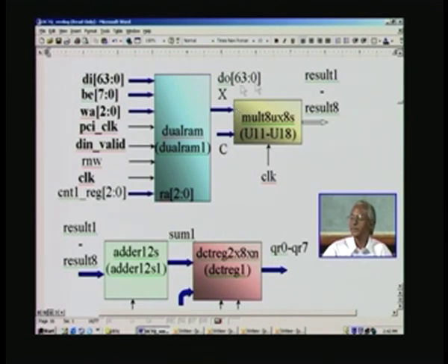The architecture will have to reflect this parallel algorithm we have developed before, and the same nomenclature is put at strategic points for you to grasp what they are. Only remember that one row of the image is applied at one point of time. At every positive edge of this clock we will keep on changing to a new row. That means it is pumped at a very high rate of the system clock.